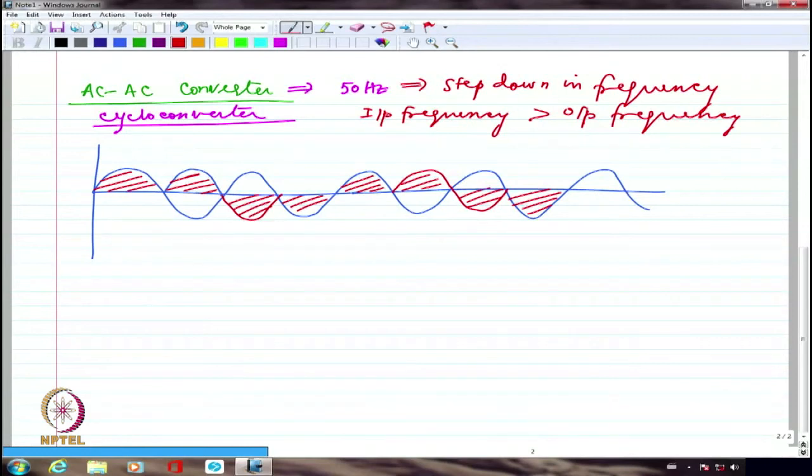I cannot do this with diodes, I hope you understand, because diodes will conduct no matter what if they are forward biased. So I can't even have a dual converter with diodes. I can't connect them back to back. It is going to essentially burn completely, because one will have plus on the top and minus at the bottom, and the other one will have it the other way around, so you would be trying to connect the plus and minus together. Imagine the dual converter. I am talking about a dual converter, so I am going to have something like this, single phase.